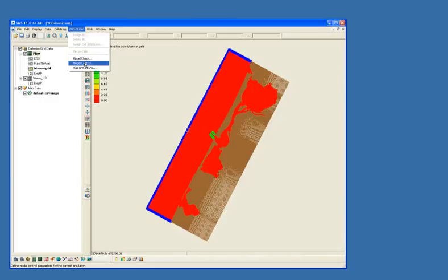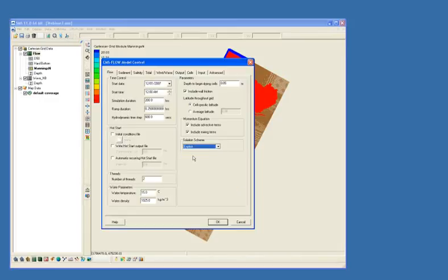and I'll go under the flow model and change to explicit. And then I must change my time step because there's no way the explicit model is able to run at a 600 time step. So just to be on the safe side, I'm going to run with a 0.75 second time step. I'm not exactly sure what should be used here. It's just you run something, and if it crashes, you try a different time step a little bit lower, and hopefully that runs a little bit easier. It's a little bit more difficult to figure out what the appropriate time step is.